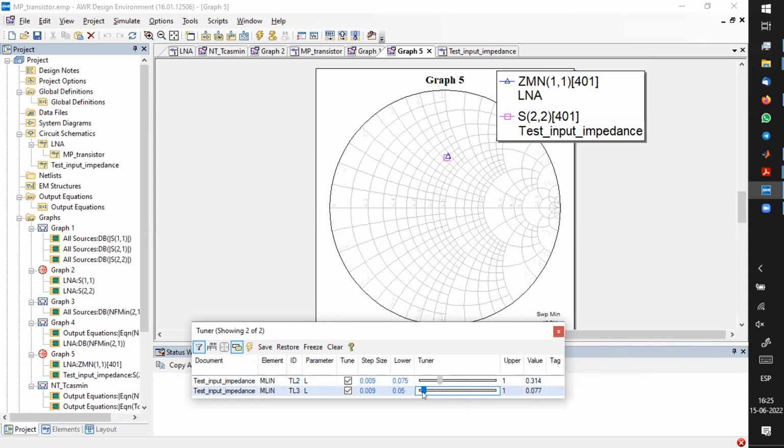But one thing in my slides was that if you plot the noise circles, so the versioning of the noise, actually you don't need to hit exactly. You can be a bit below to make it more wideband. We don't get that much hit on the noise figure, but you can stay there. So that's the input matching. Now you would take this input matching network and put it back to the LNA.